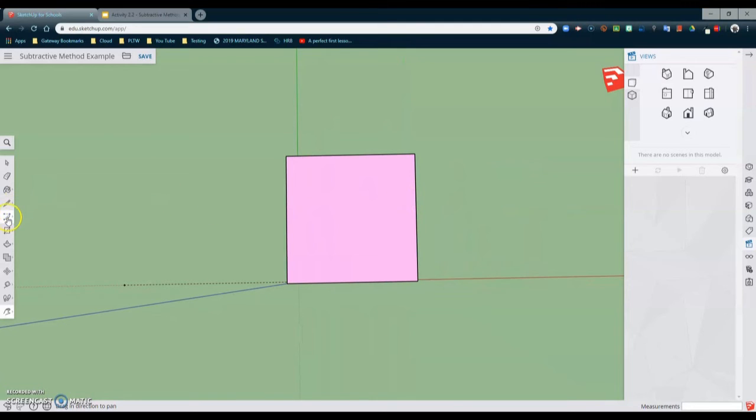We're going to use a new tool here called the rectangle tool. In previous examples, we used our line, and now we're going to go down and select that rectangle. Make sure you select rectangle, and we're going to start in that upper left vertex. We're going to click once and drag that rectangle out. Now before we click on anything and set our parameters or our dimensions, what we're going to want to do is type these in.